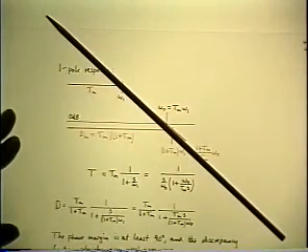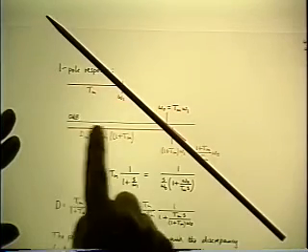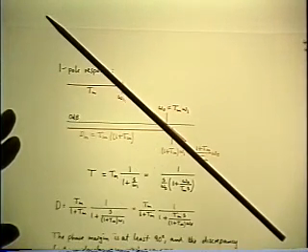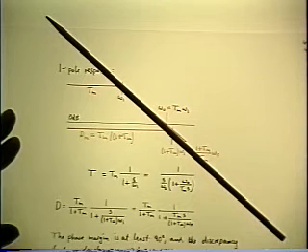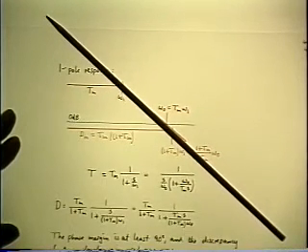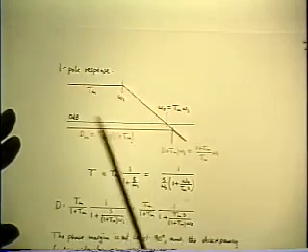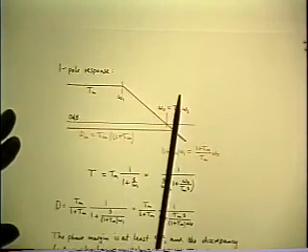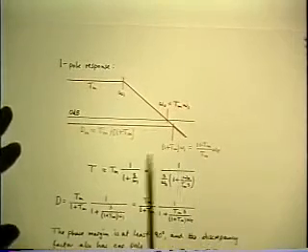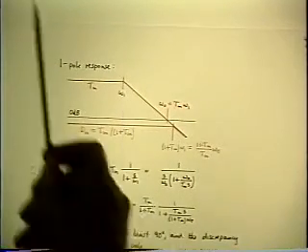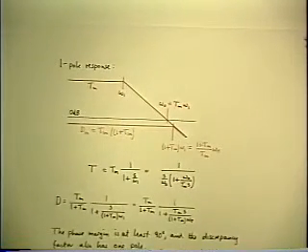What happens to D if we do that? It gets to 0 dB, flat. That's a simpler case, and we don't need to worry about the little wiggles anyway. So let's simplify the problem by pushing the omega 1 corner off the picture.